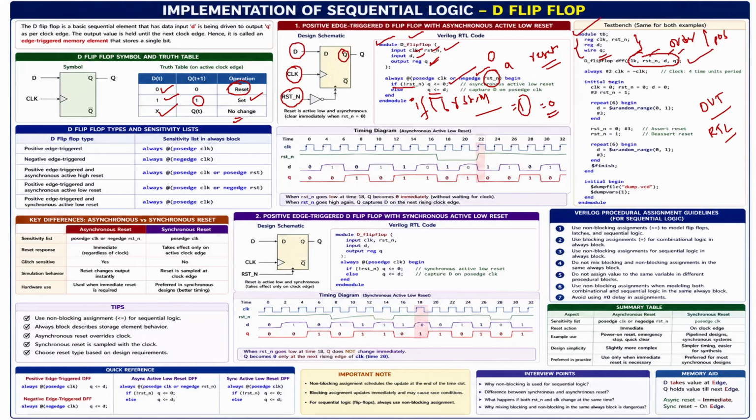For input, you can represent the wire data type, or sometimes you can use input only without using wire or reg. But for output you need to represent reg, because input default values are wires only. If you do not mention it, by default it will take the net type. Wire only it will take.